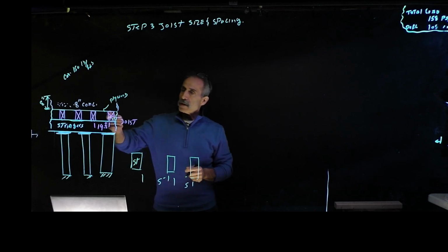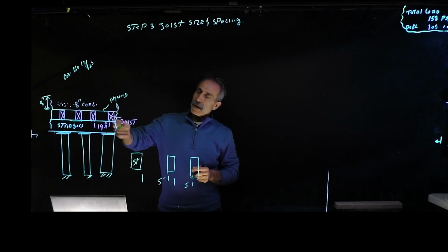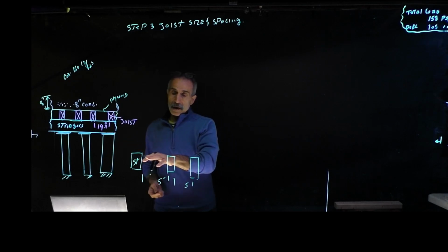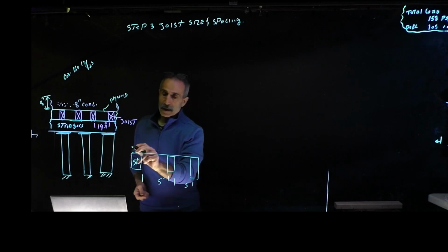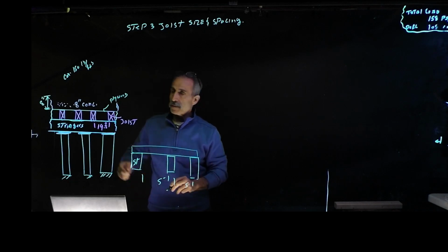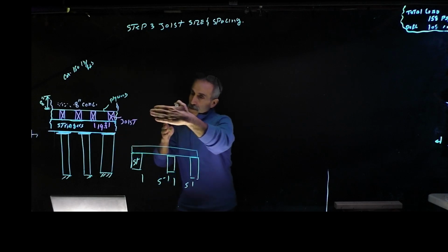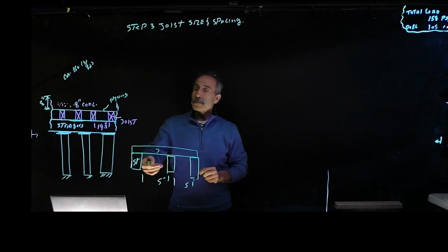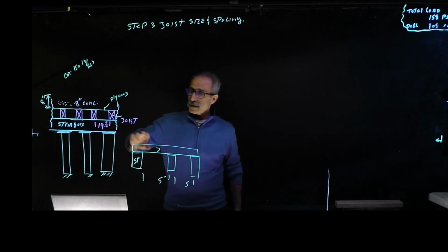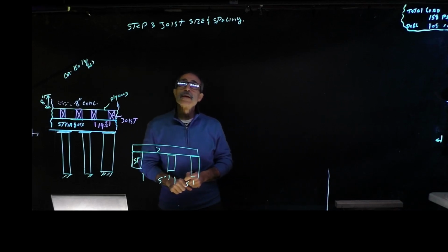So whatever number I have, if I get a 10-footer, that means I'm going to have a 3-span. It's going to go across, 3-span, and this will be the joist if you look at it from the other angle. So it's going to go multiple 3-span. We're going to design this using Douglas fir large.